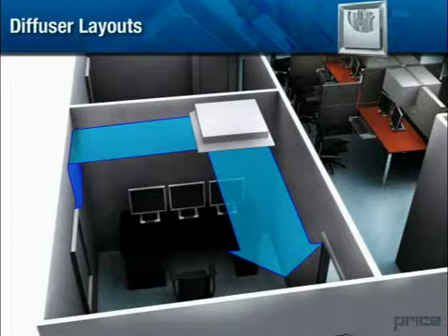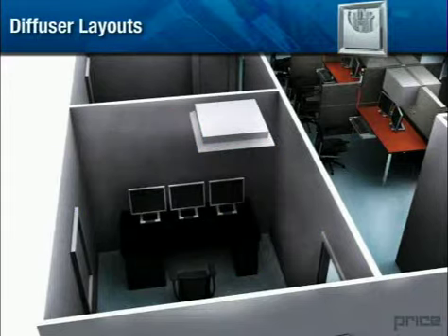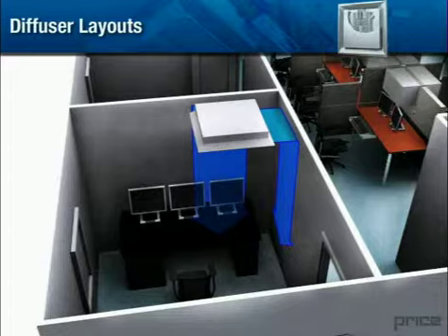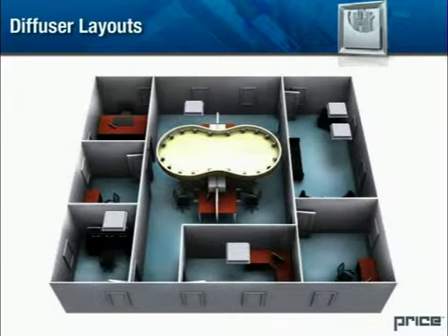The diffuser is designed to throw the air along the ceiling for a predetermined distance. Air coming out of the diffuser on the side facing the corner will hit the wall and move downward along it at a high velocity. This may create drafts in the occupied zone.